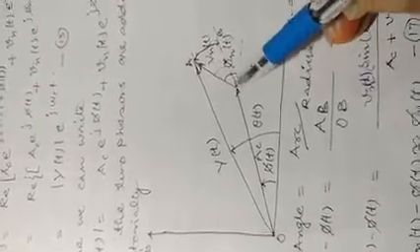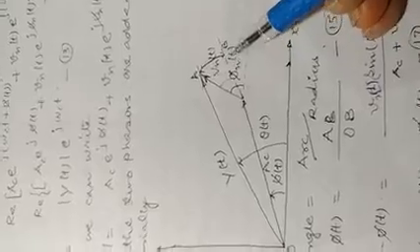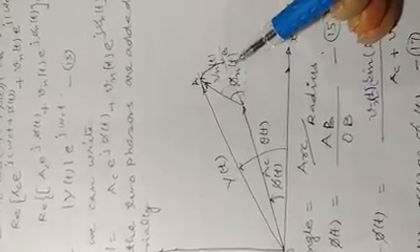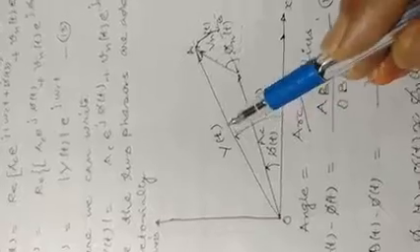If you see, this is a small arc, and it is approximately the same. We have extended it because V_n of t cos(phi_n of t minus phi of t) is very small, but if we add it, we get A_C plus V_n of t cos(phi_n of t minus phi of t). This will act as the radius, and this will act as the arc, and we can find the angle between them.